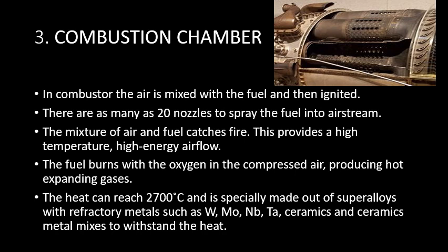The third part of a turbofan engine is the combustion chamber. The high pressurized air from the compressor is then passed to the combustion chamber, and in that combustion chamber, that air is mixed with the fuel and then ignited. As we know, there are as many as 20 nozzles to spray the fuel into the airstream, and thus the mixture of air and the fuel catches fire. This provides a high temperature, high energy airflow.